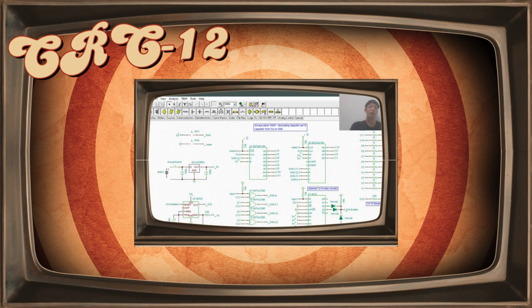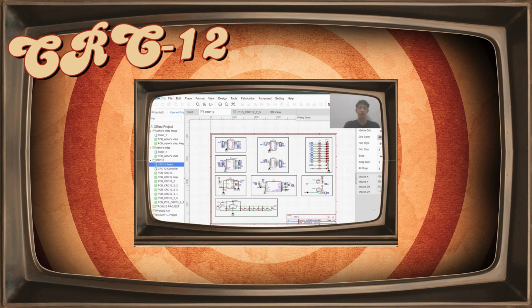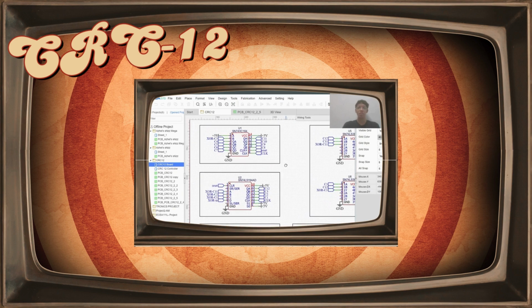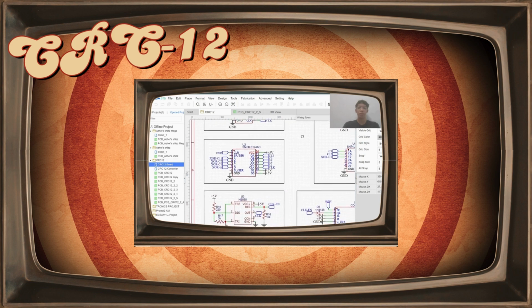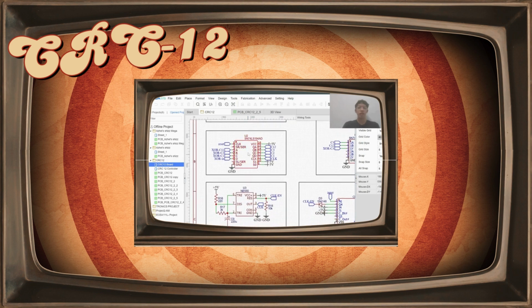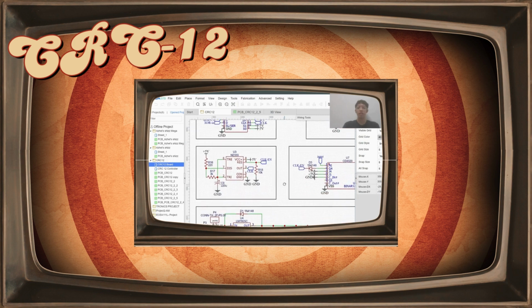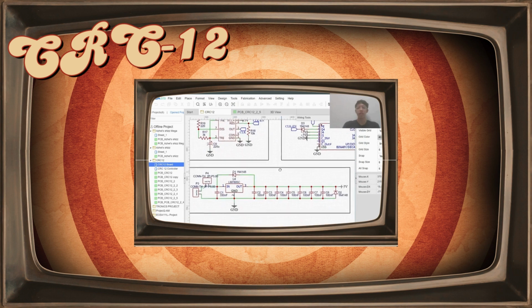Now let's move on to our proper and actual schematic, which is in the EasyEDA application. Now here we are on EasyEDA, in which I'll be showing you our actual schematic for our PCB design. So we still have the same flow. We have the 164 IC for our serial input, parallel output shift register. We also have this 74194, just like what I've shown earlier. We still have the 555 timer.